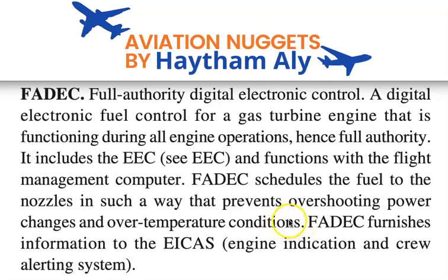Also, the FADEC furnishes information to the EICAS, engine indication and crew alerting system, EICAS or ECAM, electronic centralized aircraft monitoring. So the FADEC always furnishes information and gives it to the engine indication in the cockpit, the engine indication and crew alerting system, like EICAS or ECAM.